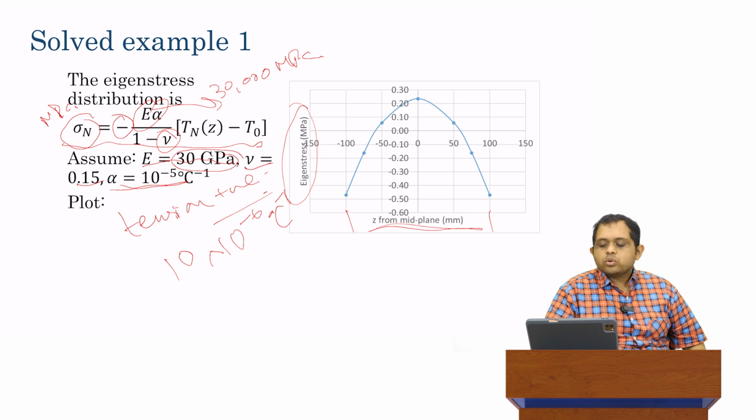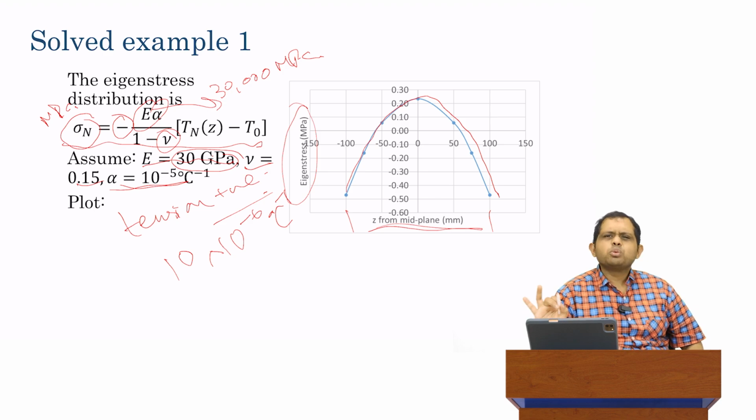What we will see here is we do get a parabolic sort of shape. That's actually quite expected. Our original distribution was parabolic to within 99.75% of variance. We decomposed it into some kind of a rectangular or constant distribution, and a linear distribution. So whatever is left has to actually be parabolic, so that when we sum them together, we recover a parabola. So in this case, our eigenstress is parabolic in nature.